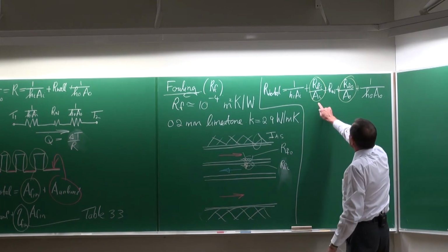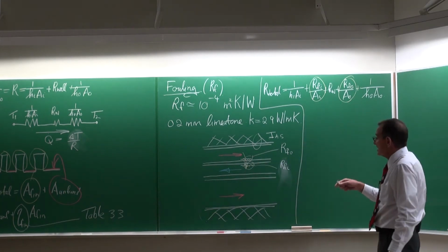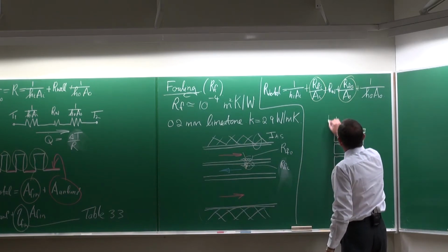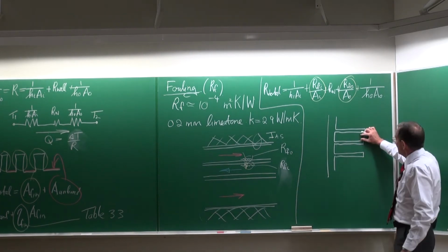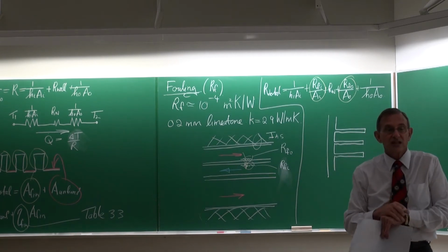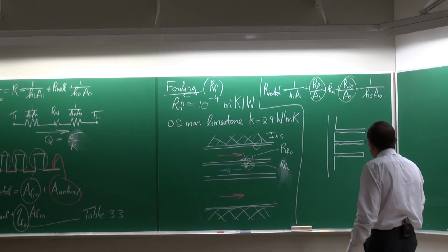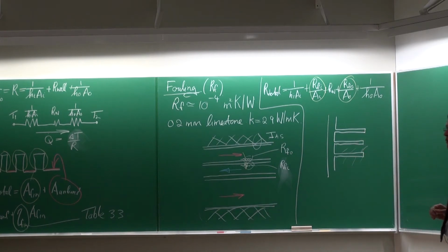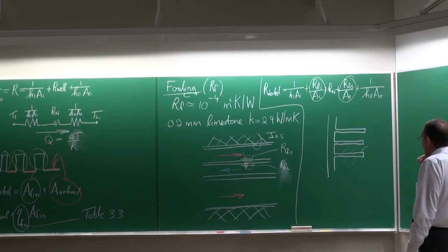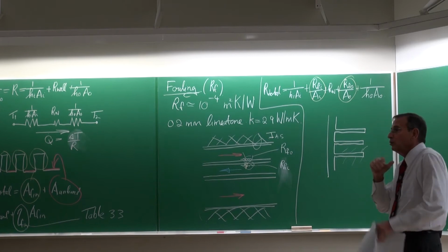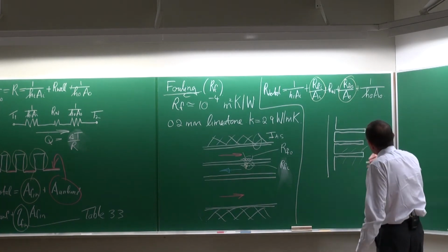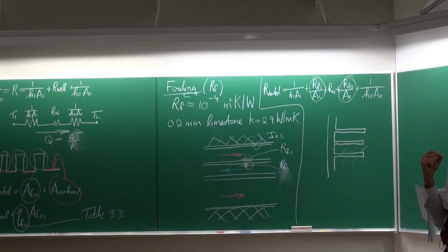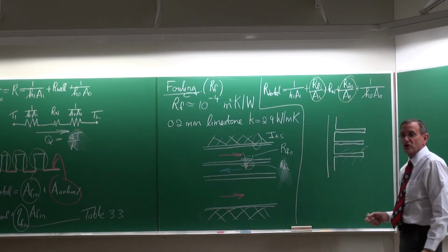You do get these fouling resistances not only in systems where there are liquids, but you also get them on fins. Obviously I'm drawing these fins far apart from each other just to make it clear, but normally these fin distances are 1 to 2 millimeters. You can go and look at many condensers or evaporators on the sides of buildings. After a few years, you will see lots of dirt and leaves and many things that can cause this additional fouling. Also with fossil fuel power stations, especially the dry cooling type, where they've got big fans that increase the heat transfer by blowing air over all these fins, things like moths end up between these areas, and they can really clog it up very, very badly.